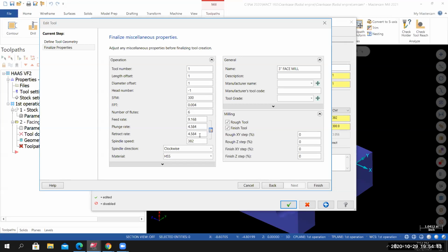Yeah, for sure it does. Okay. Like the place where I work, tool 24 is the probe that's always there, and tool 20 would be the face mill that's always there. So we have the 3-inch face mill in the tool 20 slot, and what usually changes is the insert, depending on the material that's being cut.